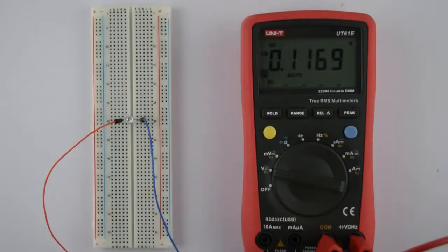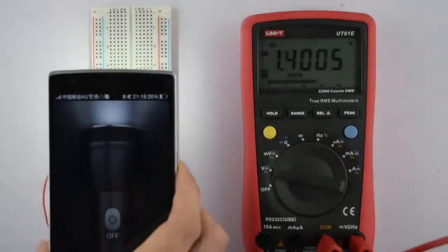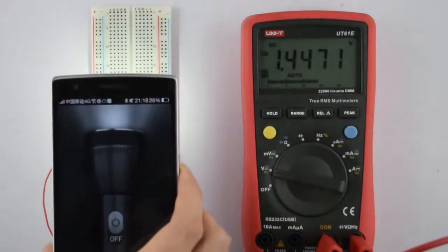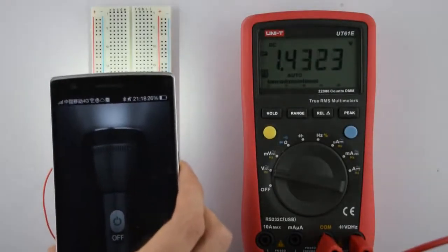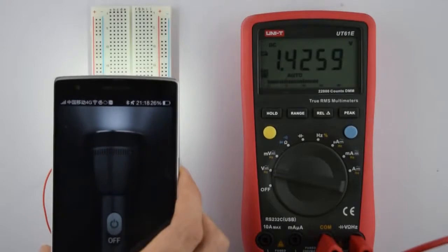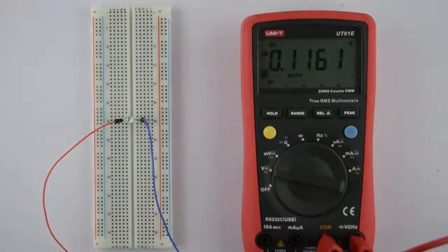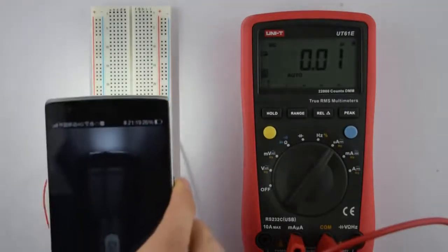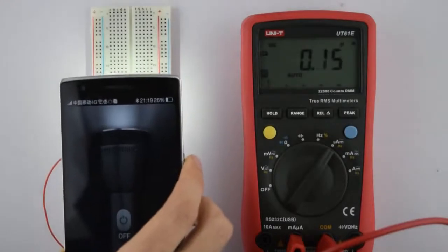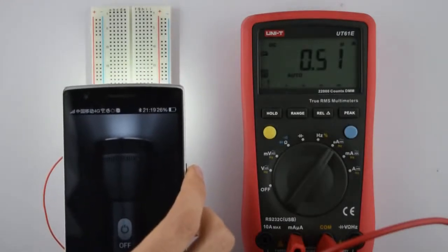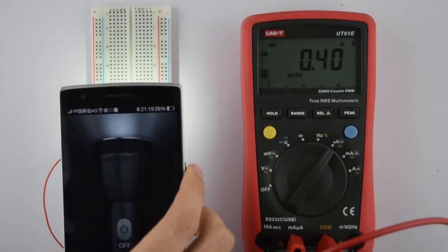Here I have a red LED connected to a multimeter set to measure the voltage across it. I have pretty bright light set up for this recording, which is generating about 0.1 of a volt. If I put a bright LED over top of it, we see that a considerable voltage is produced. Note that the voltage produced will vary depending on the light source and the LED used. If I now measure the current passing through the LED, I see that only a tiny current is passing through it. In this example, only about half a microamp.